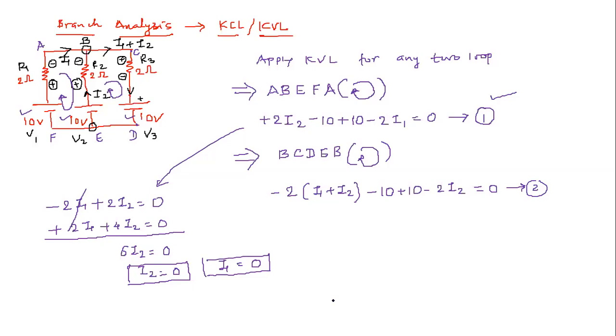So what will happen is they are not able to supply the current because they are of equal potential, right? And we know that current always flows from higher potential to lower potential. But this B point is at equipotential. Are you getting my point? See, this B junction is at equipotential. Whatever the potential at this point is the same. You can imagine the circuit like this, no?